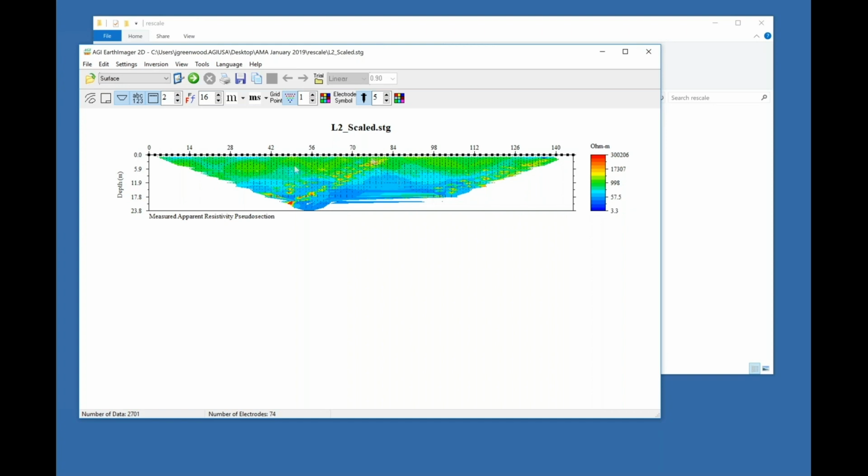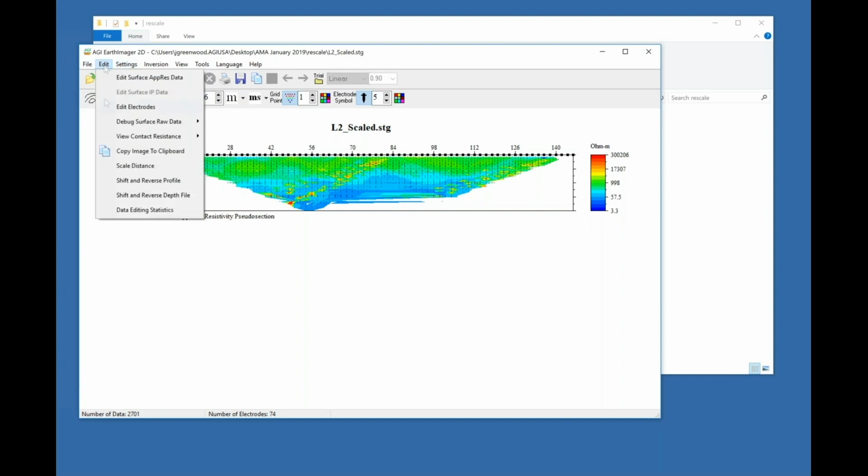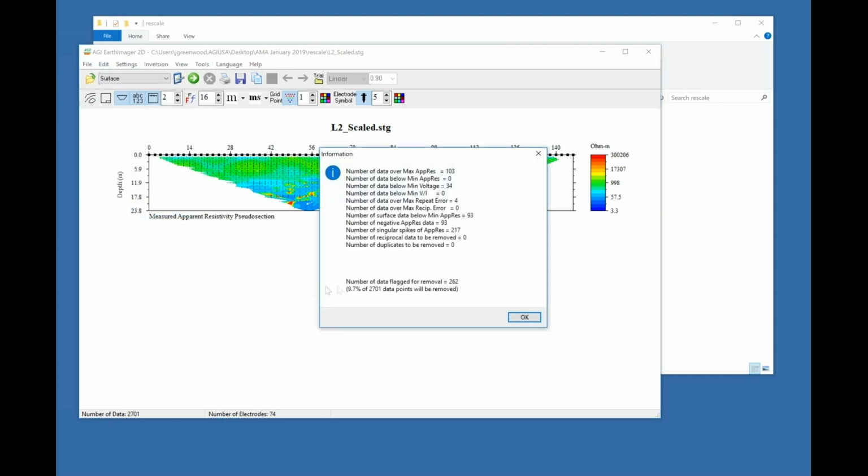So either the connector at number 1 or number 56 is dirty or damaged, because this shows up once they roll.